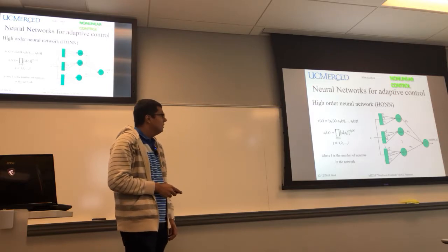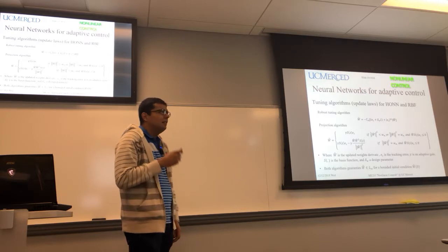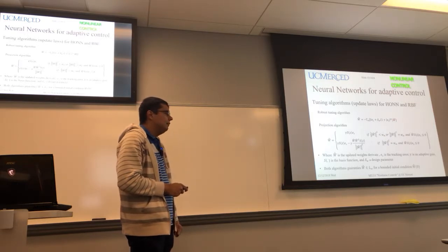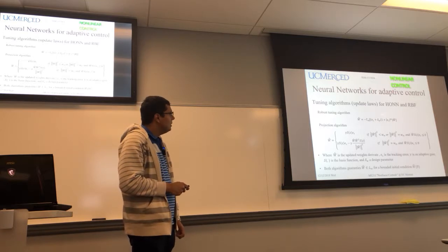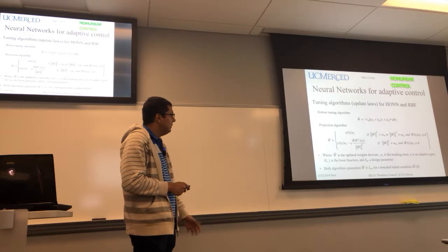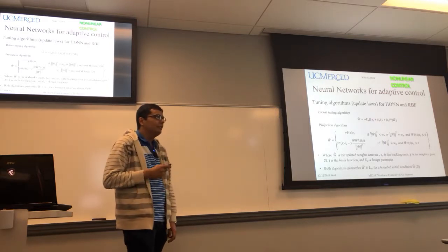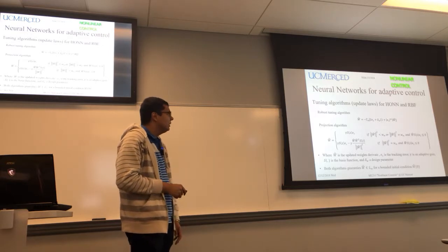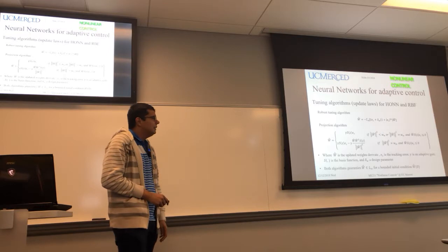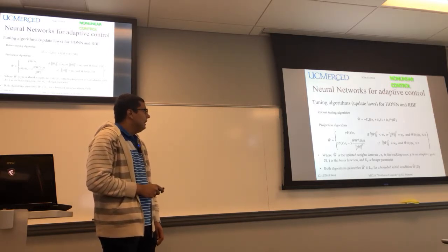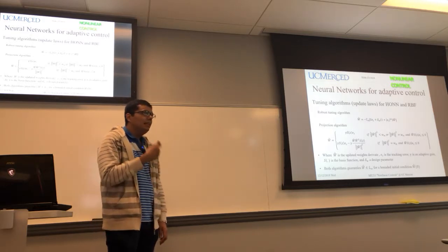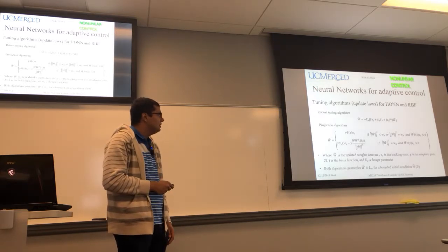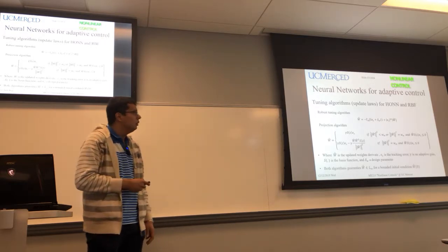that we have here. In this case, this is a basic robust tuning algorithm. Those techniques or update laws basically weight the current W, the current weights, using the radial basis function. This e_s is the sliding surface term, this delta omega is a tuning parameter, just like a learning rate of our neural network. We have this gamma, this is another tuning parameter that we could employ. The advantage of this kind of tuning algorithm is that they are robust and stable. The book has a big demonstration about how this law is stable in closed loop.